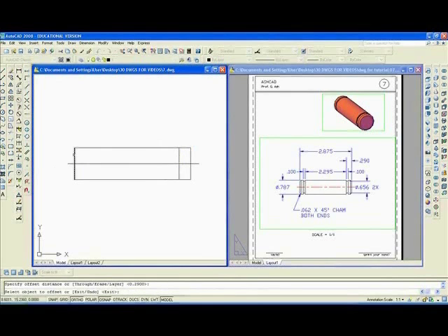0.29, just keep hitting enter. Hit enter twice to repeat the command, and this time I'm going to offset 0.1. Offset in that direction, 0.1 in that direction. Next, I'll want to offset, I'll hit enter twice, a distance of half of 0.656, which is 0.328. So I want to offset 0.328, enter, this line going up here and down here, and then I can zoom with the window